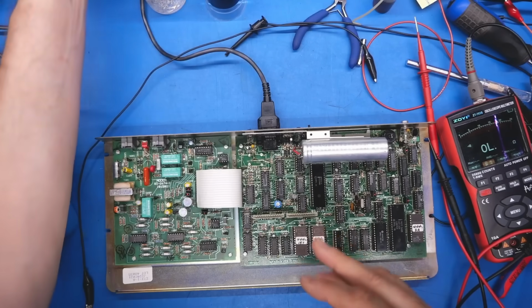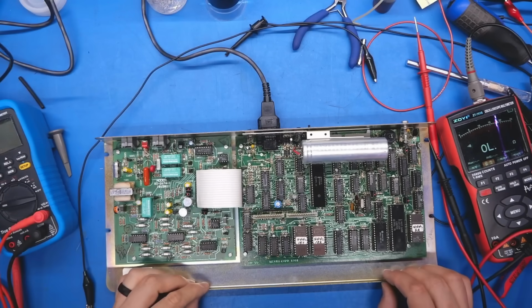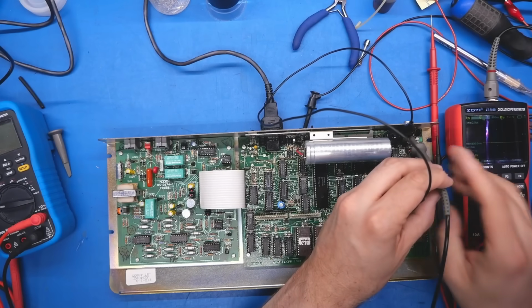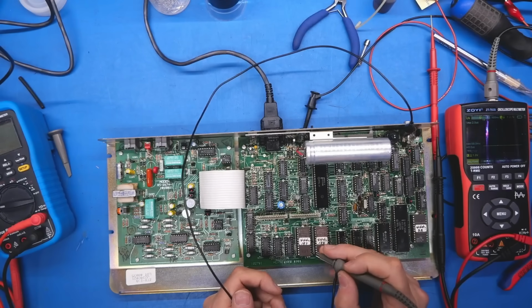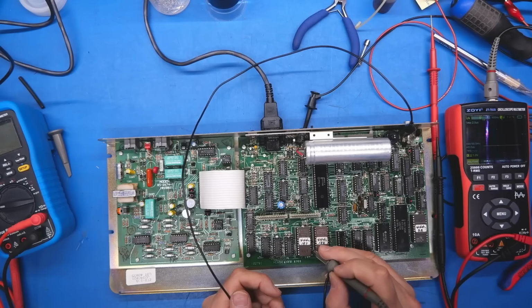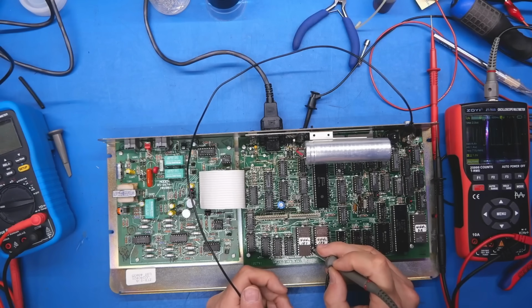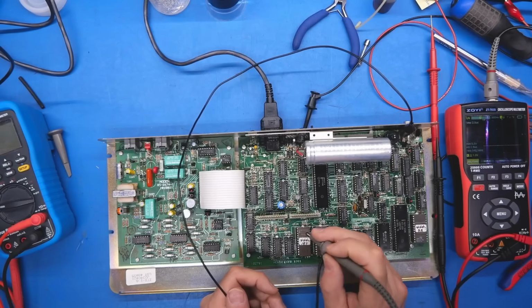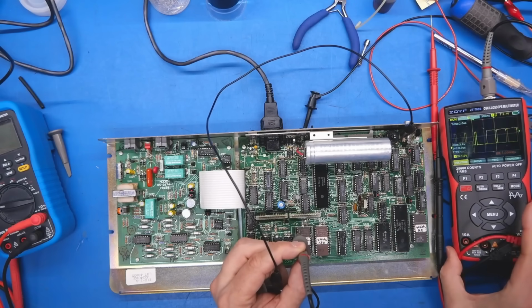And let's just try one more time with the power supply. No clicking. And 800 millivolts on the video output. So without a doubt, we're still in the same exact spot we were before. Yeah, lots of activity, data bus, and activity on the address bus. Sorry, you can't really see that.